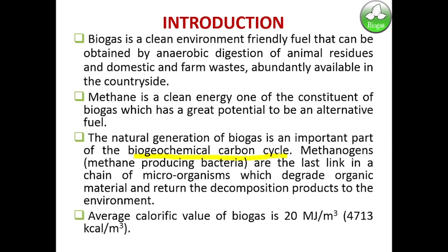Second is the digestion, which consists of both aerobic and anaerobic biological processes. In the digestion process, as we have already discussed, due to the presence of methanogenic bacteria, the biomass is converted to methane through degradation by these bacteria. These biological processes are again of three types: hydrolysis, acidification, and methanogenesis.